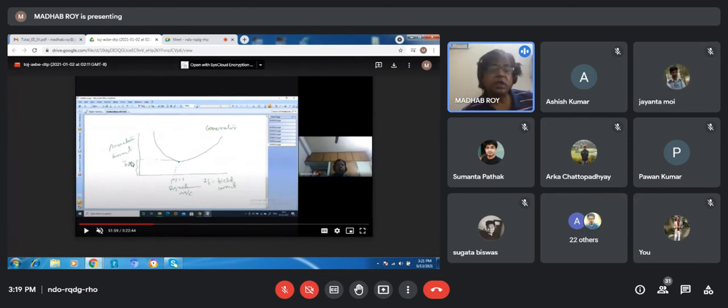For this, what we have to do basically? One axis is the armature current, that is the synchronous generator armature current. Another axis is the field current, that is also the synchronous machine field current. The starting point is here. This armature current is related with the loading. So this armature current will decide how much load is there. And this point will decide the 2-wattmeter equal reading. So that is the minimum power delivered from the generator, and this minimum power is basically the point of